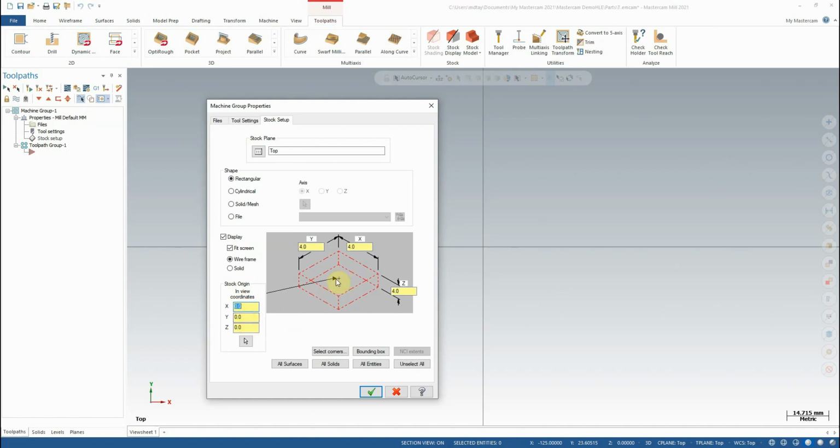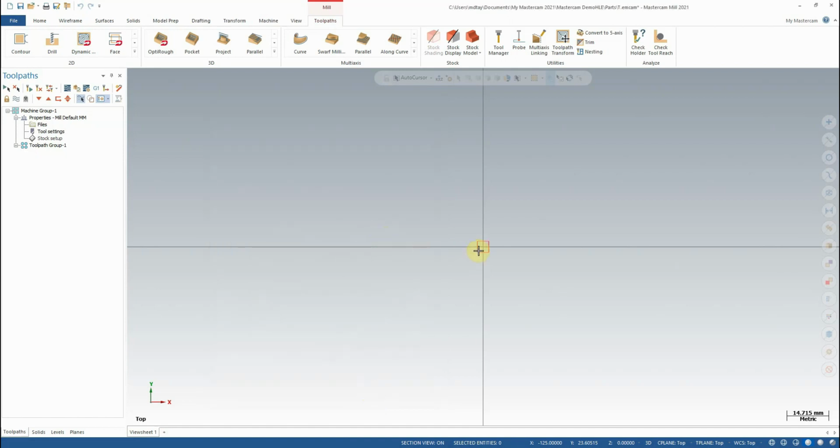So this point can actually be selected. You can click on any point of the stock model, any of the corners or the center, in order to set that as your datum. Generally we work with the center or the bottom left corner primarily. Both of the projects within this course will be working from the center. So when you select the center like this, you can enter your stock values here and press OK to continue. A couple quick notes, however.